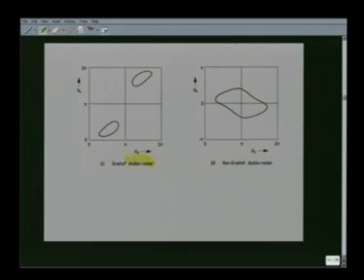If we have a Grashofian double rocker, then again we have two loops, one as we see here and the other there. Because this is a double rocker, neither theta 2 nor theta 4 can make a complete rotation. So, they are limited between two extreme values. For example, theta 2 from here to there, and theta 4 from here to there. Again, there are two distinct loops for two different modes of assembly. Either you are following this curve or you are following this curve. You can never pass on from one mode of assembly to the other.